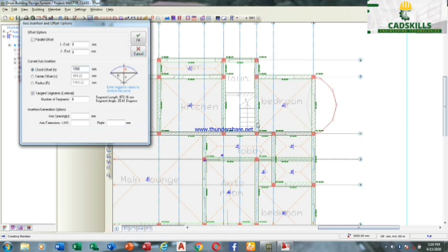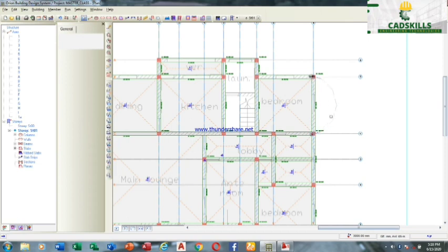If I'm okay with it, how do you match this curve with the one the architect put? From this place to this place, get the middle. When you get the middle span here, draw a line from that middle and hit the curve that the architect has drawn. When you hit the curve, take your dimension from here to that place. Whatever you get, that is what you put here to give you that curve. Is that all right? So when you have done that, click OK. It will put the axis. The axis has already been put.